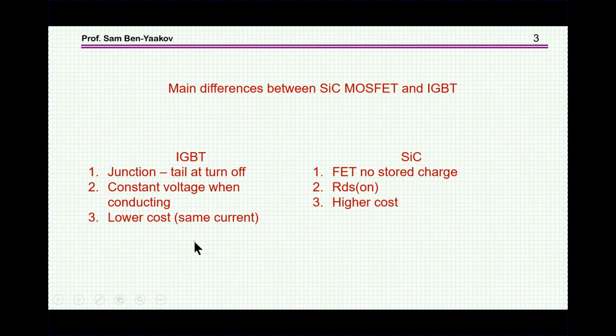So the comparison is really not that simple. If you just compare devices of the same current capabilities, not considering the switching frequency, then the IGBT is much less expensive. But of course, if you bring in the issue of switching frequency, then it's a different story.